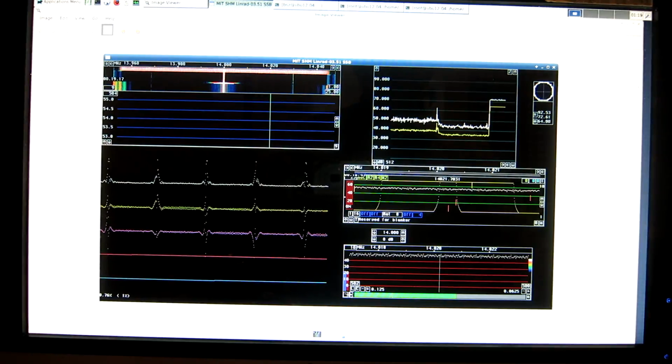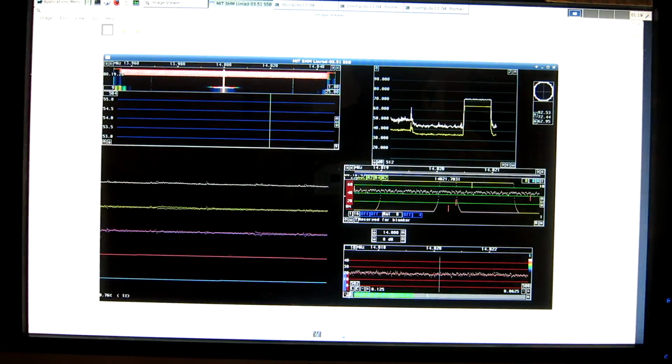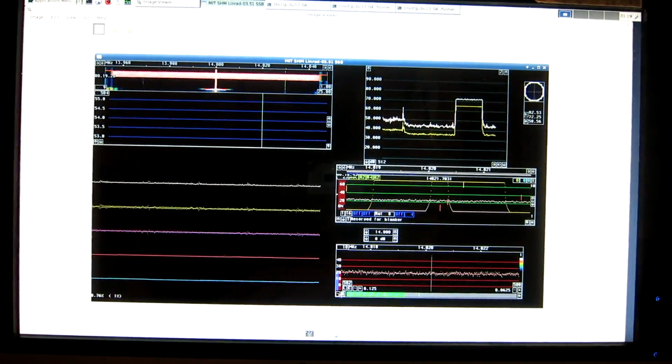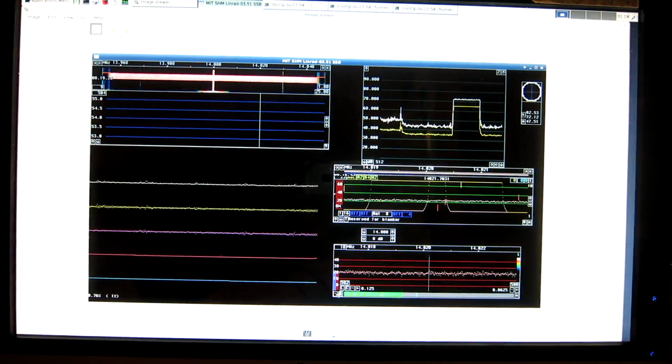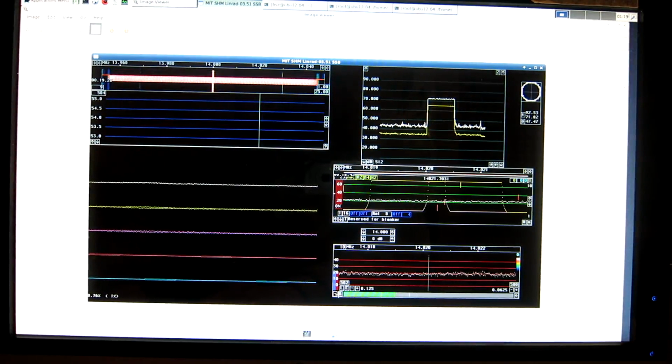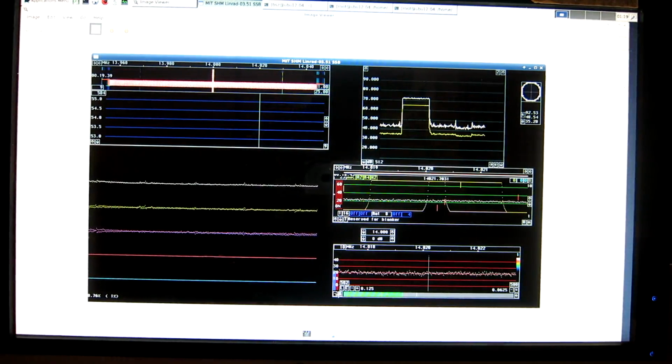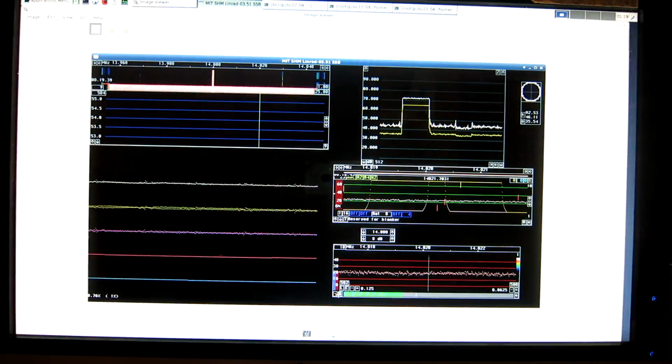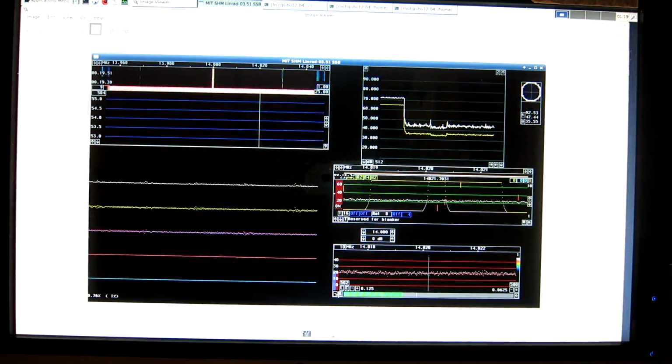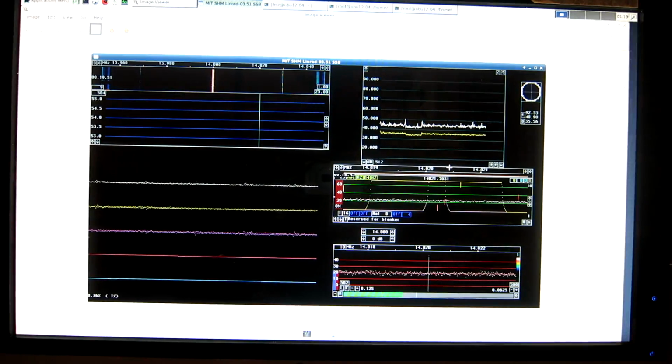And you see now the smart blanker, and switch off the pulse generator, and it's only 1 dB. So I have an improvement of 30 dB, but the remaining interference is only about 1 dB, as you can see here, maybe 2 dB.